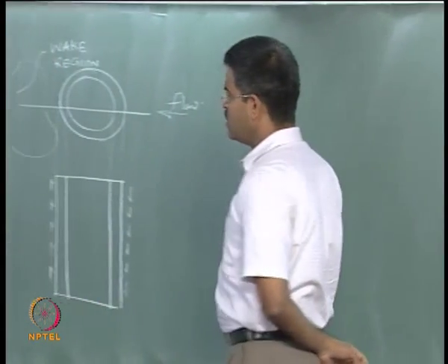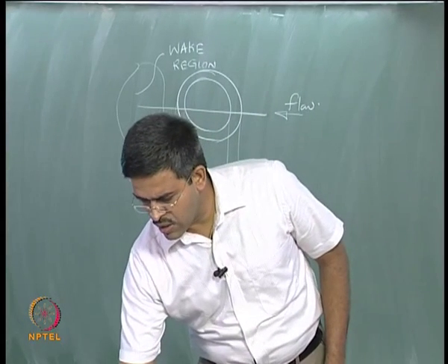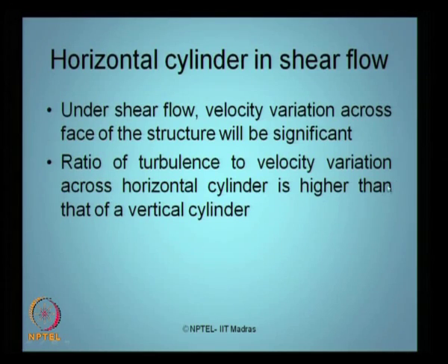So if you have an offshore structural member which is an assembly of horizontal and vertical cylinders, then the vibrations induced by the flow field, because of the interference between the vertical and horizontal cylinders, will have a different domain of vibrations, and the effects on the horizontal cylinder are going to be different near the free surface compared to the depth located from the free surface.